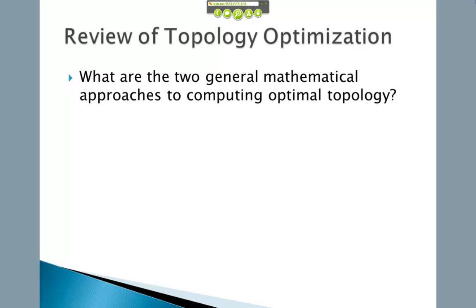And what do we do with that? We drop it at every point in the finite element solution that has what? Low or no stress. Very low stress or no stress. And what do we do? A subtraction function. Okay? And so we just eat away in a discrete way where all of the zero stress points are, and that gives us a topology optimization. Okay? That one's discrete, right?